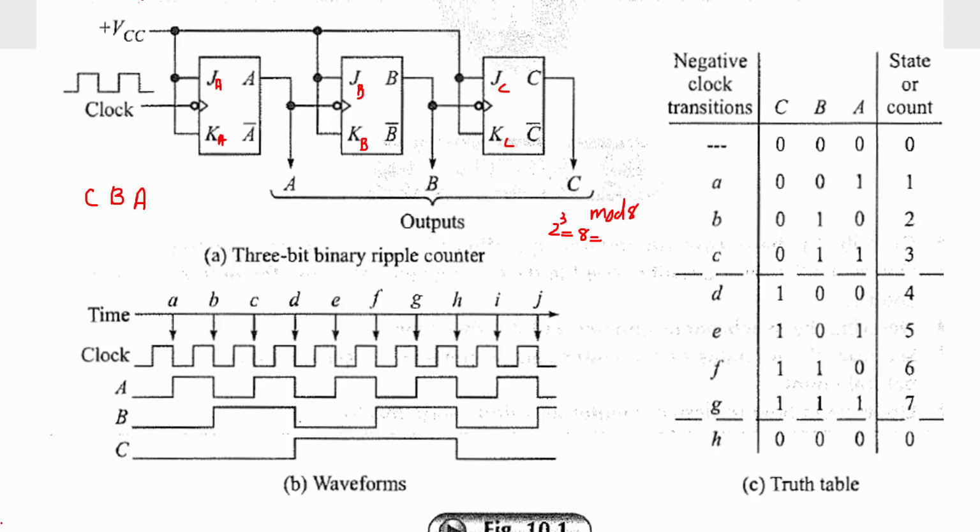Okay. So what is the meaning of this clock cycle? Here, see that the clock representation, bubble and arrow, means we are assuming negative edge triggering. So this particular flip-flop output is generated based on the negative edge of your external clock. So which one? A. The A output depends on the negative edge of your external clock. During the negative edge of that external clock pulse, A will toggle.